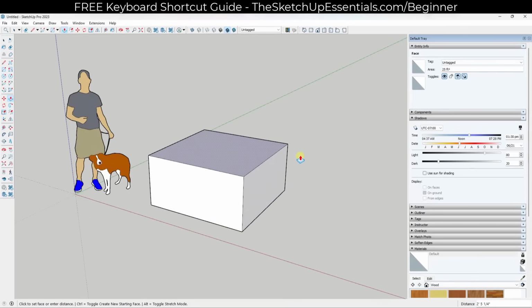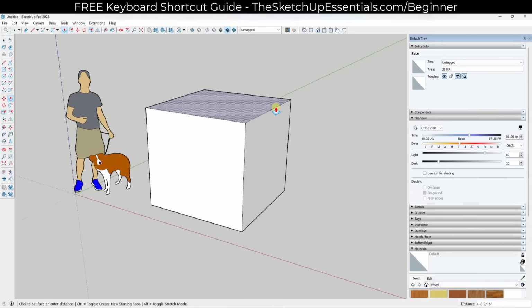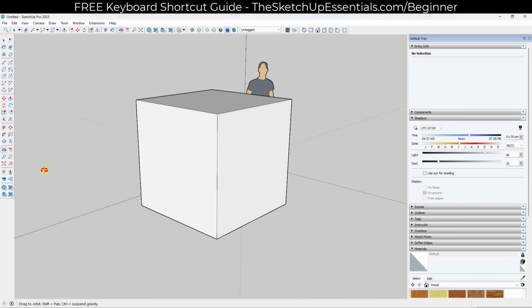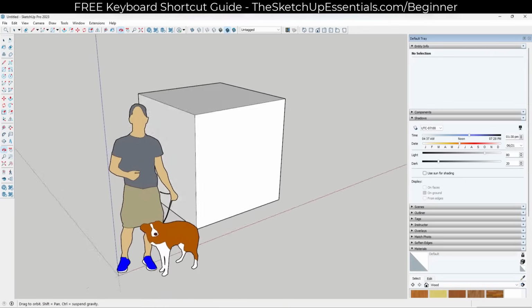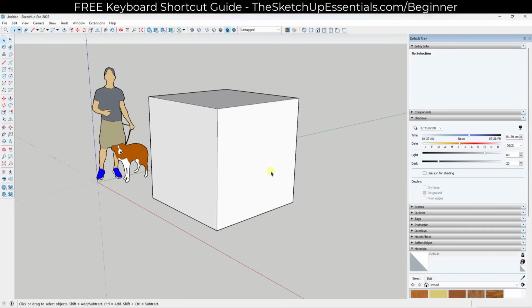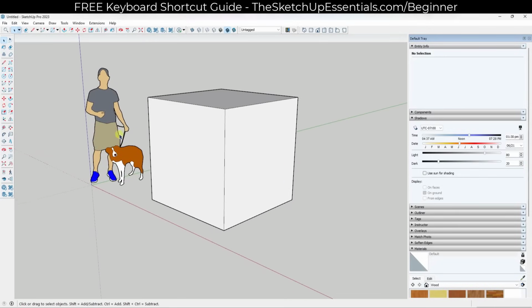Notice how now, if I move my mouse up or down, this is going to extrude this shape into 3D. And notice what it's doing is exactly what we described, right? It's taking this face, moving it into 3D and creating supporting geometry around it. In this case, we can either click to set this, or I'm going to type in a value of 5 foot and hit the enter key. And so what we've done, if we orbit around this using our middle mouse button, is you can see that we've created a cube inside of our 3D space. Extruding things like this into 3D is really easy.